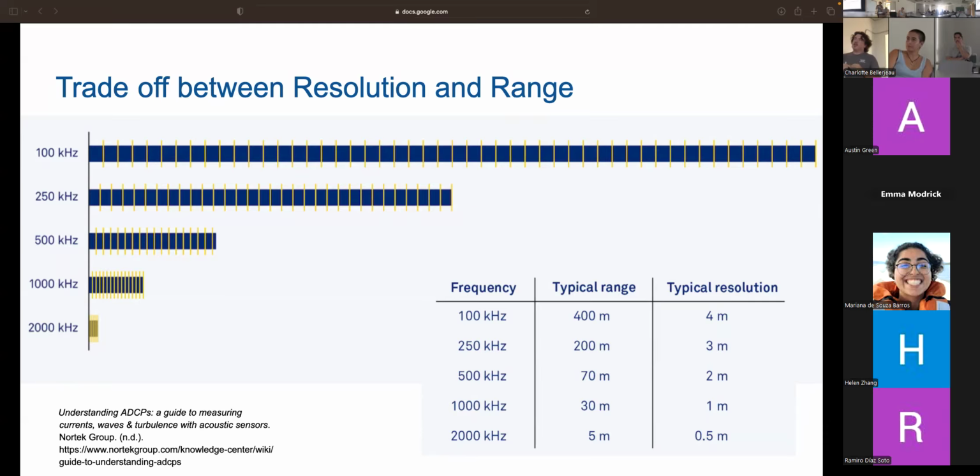And you just have to be really careful, but yeah, using the demo again here. Generally with flow going by, you're going to get a little bit of a boundary layer across the face. But you just want to have the space far enough that the flow is generally not interrupted. But if you're trying to measure something from the backside, that's where you start getting into considerations.